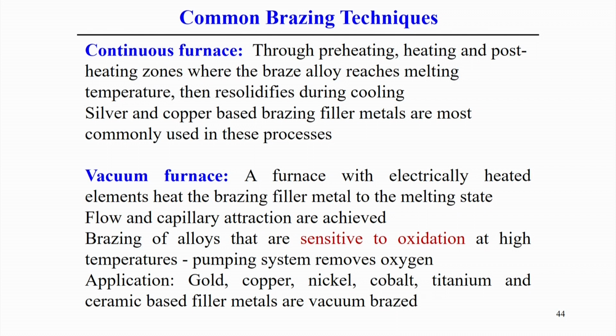Another type of brazing technique is the vacuum furnace. We use a vacuum furnace also for the brazing process. In this case, it is a furnace with electrically heated elements, which are part of the furnace, and it generally operates under vacuum. In this case also, the flow of the liquid braze alloy and capillary attraction are achieved, even in vacuum furnaces.